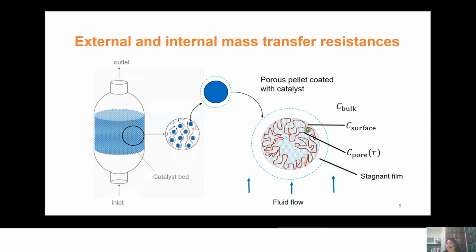So we capture those different types of diffusion using our effective diffusivity. The effective diffusivity takes into account the fact that your pore channels may be of irregular shape and size. So that takes into account the tortuosity, because the pore channel may not be a straight line, or most likely it will not be straight. And you also have the pore constriction, which is the ratio of the smallest to largest diameter. But you should know this. You know what effective diffusivity is, and then we can just model internal diffusion using Fick's law.